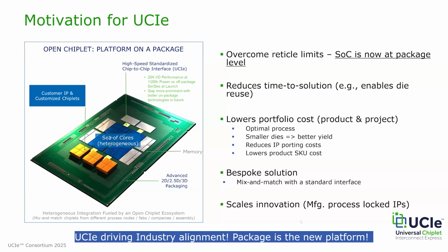So it makes sense to reuse chiplets whose functionality does not change. Cost in the advanced process nodes is high, so it makes sense to only put those functions that benefit the most from the most advanced process nodes, like compute chiplets. Other functionality, whether it is a memory controller or I/O controller, can be in a mature process node, and you can reuse the proven chiplets. Chiplets, of course, offer time to market advantages because you are reusing the proven chiplets. You are not redoing them, moving everything to a new process technology, a large chip. And you can offer custom solutions depending on the chiplet.